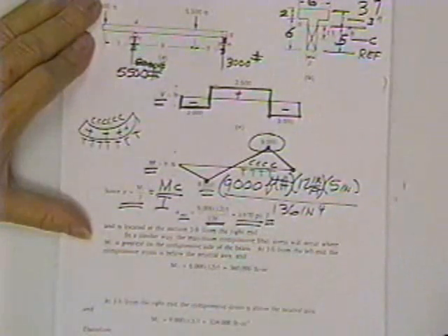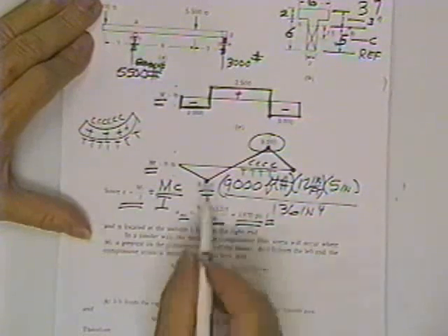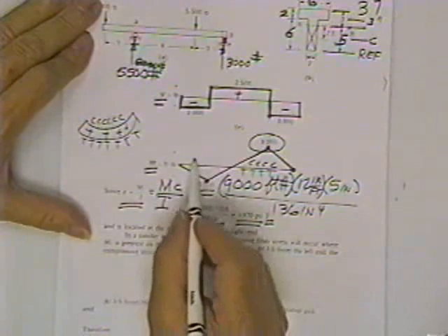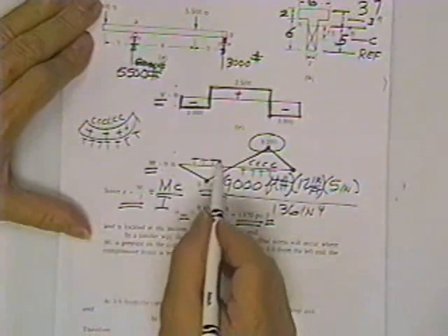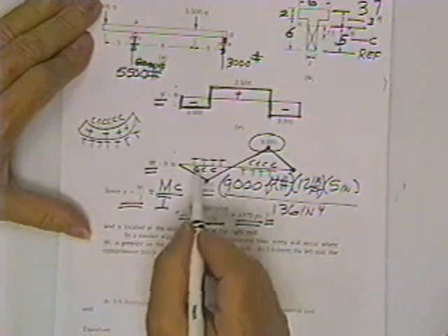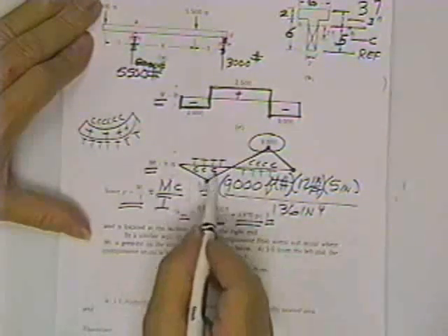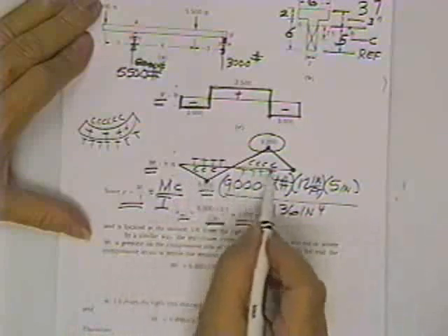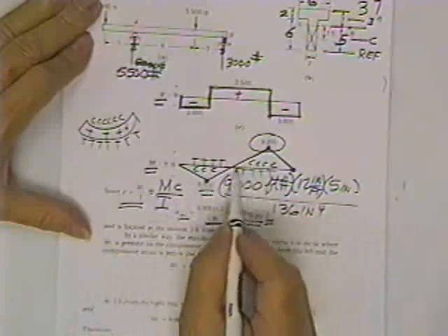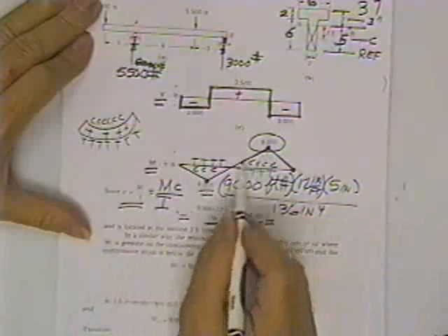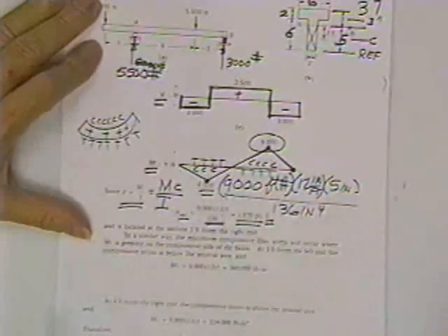It'll be very important you're able to do that. I think it'll be very likely they'll ask you whether it's a tension stress or a compressive stress. In this region, there's tension on the outside. There's always compression between the line and the moment diagram. So you can just put little C's inside, between the zero line and the moment diagram.